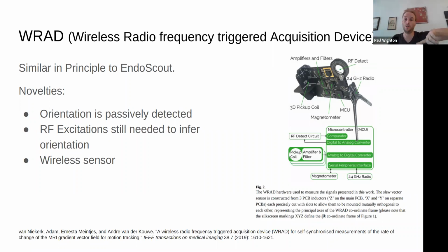So that will give you two, which should be, if the magnet's installed correctly, orthogonal. The direction vector of the magnetometer should be orthogonal to the gravity vector. And then you can take the cross product of those to get your third vector. So I think that's a really novel way to detect orientation inside an MR machine.